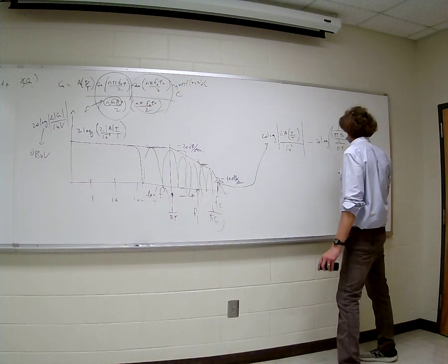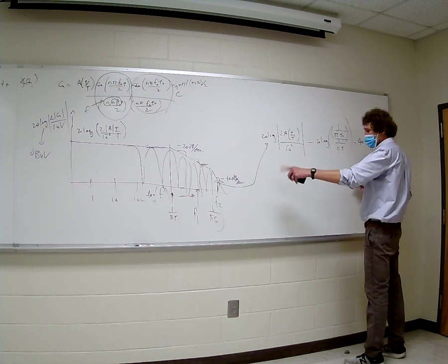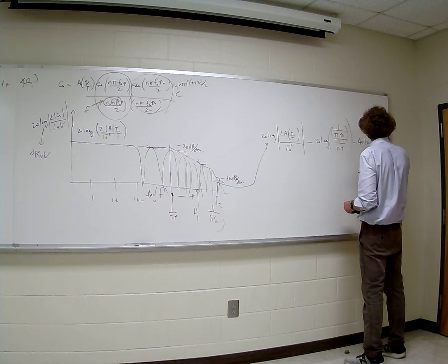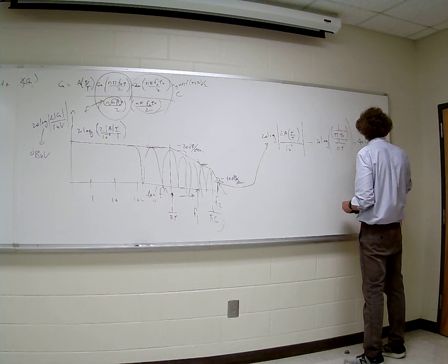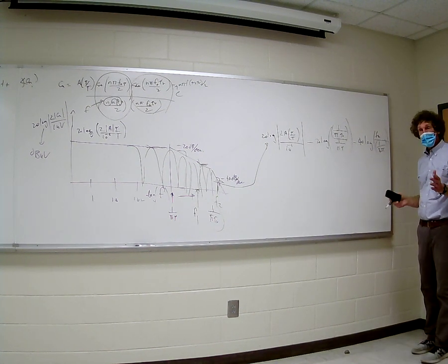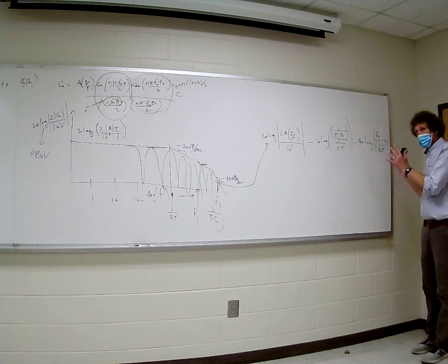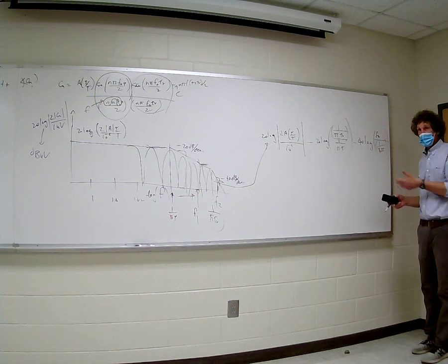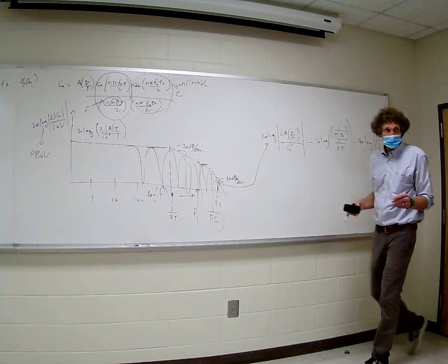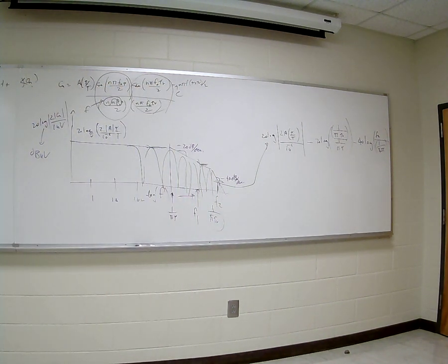And then I would have to subtract, now it would be minus 40 times the log of the frequency, in this case f2, that I ended up with, over the frequency I started. And then if you have a filter, what you have to do is find out what the dB loss or gain of the filter is and multiply it by the input signal's envelope to find out the actual value. Now that was the whole basis of all the problems I gave you. I'd like to do a few of the problems because this is so important in the real world.